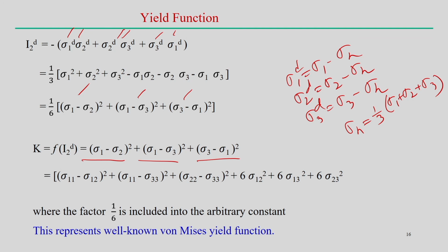Irrespective of that, the constant term can be derived depending upon the loading condition, or this can be represented in another way, in terms of all the normal stress components as well as the shear stress components, or this functional form can represent only the principal stress components.